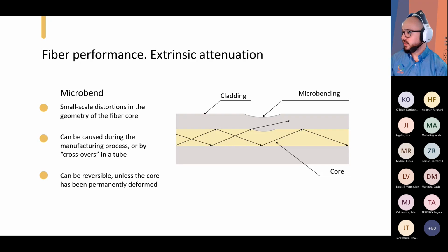Could you use two connector ends as a means to repair a splice, like a female and male end? Mike, the question is, do we need to make any fiber strain measurements after laying? And then Justin, back to your question. In theory, you probably could, but every time you introduce a connector, you introduce more attenuation.